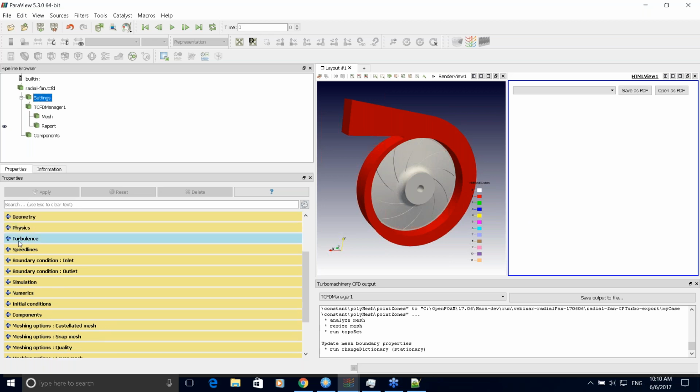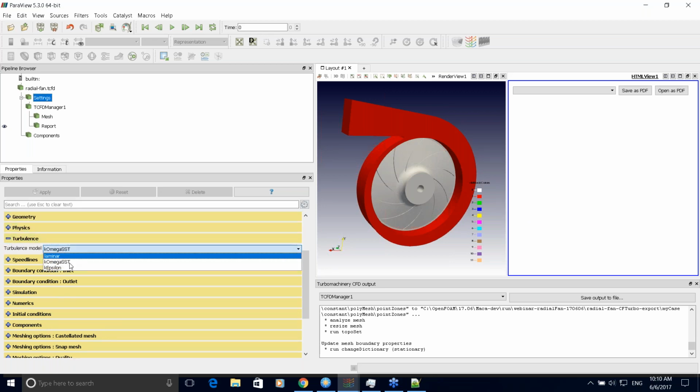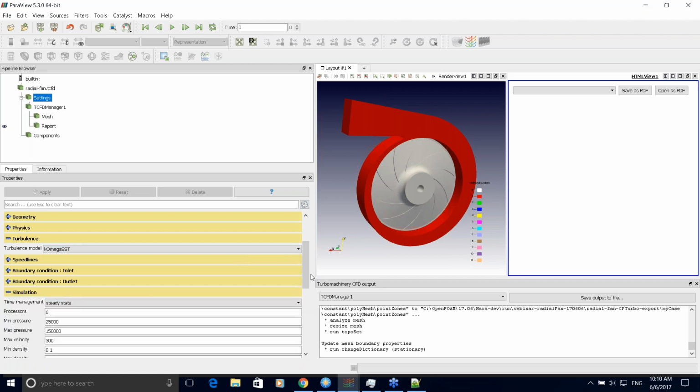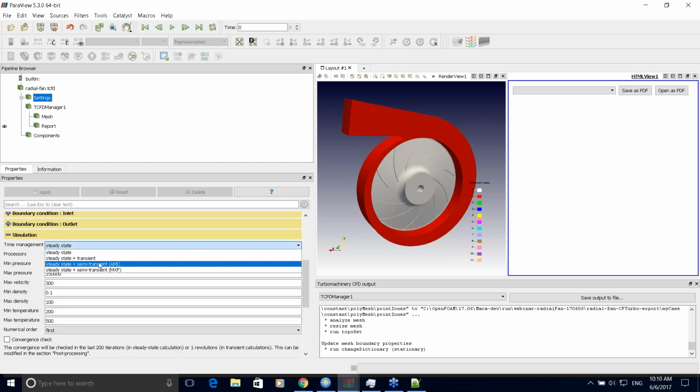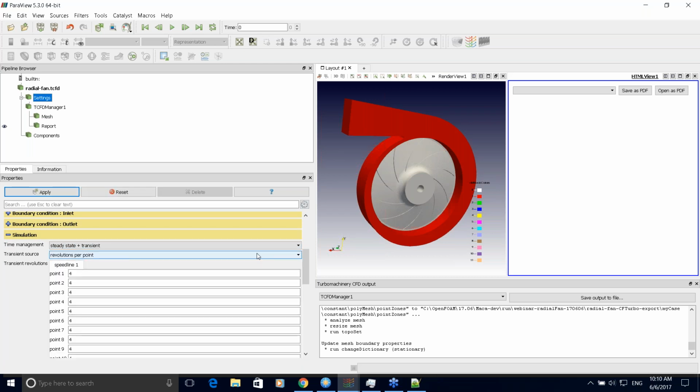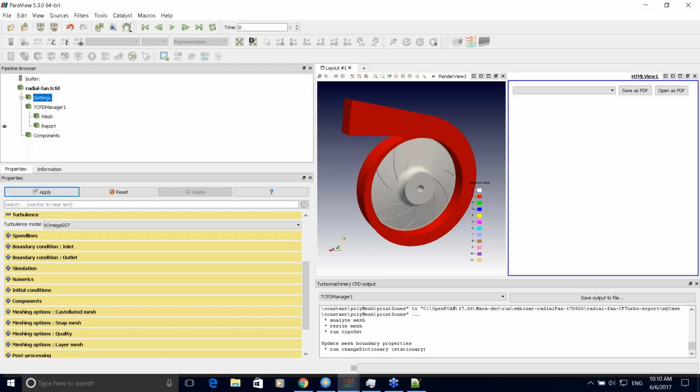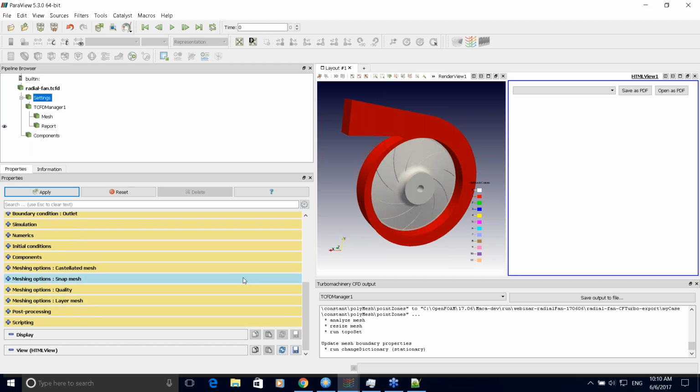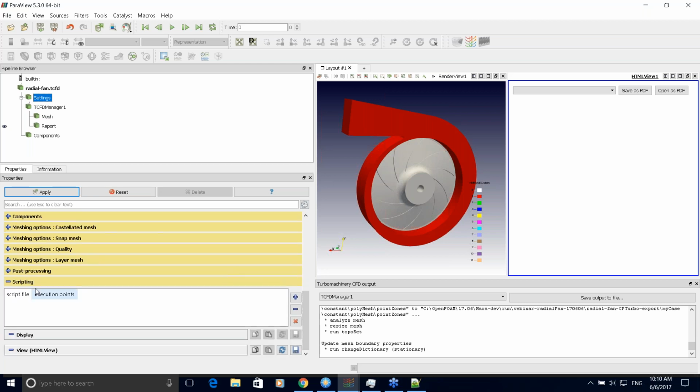Yes, it can be, not implicitly, because at this version we provide just K omega SST and K epsilon and laminar turbulence models, but we also provide transient simulations. The video you could see before the webinar started was generated using TCFD and using DES turbulence model. And I created a simple script which can change the turbulence model to DES modeling.